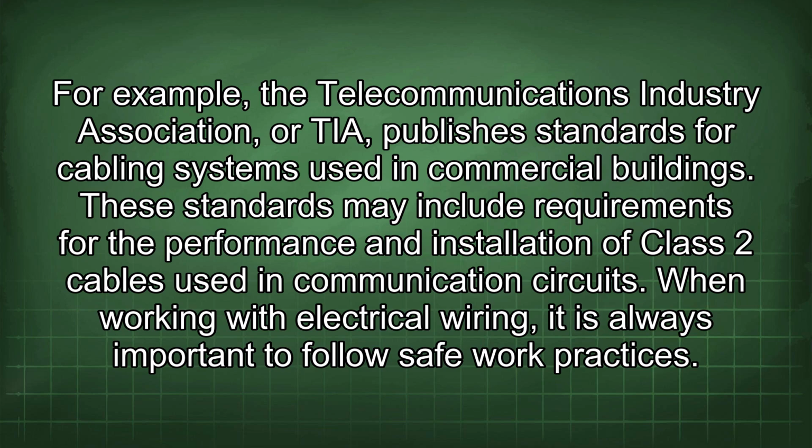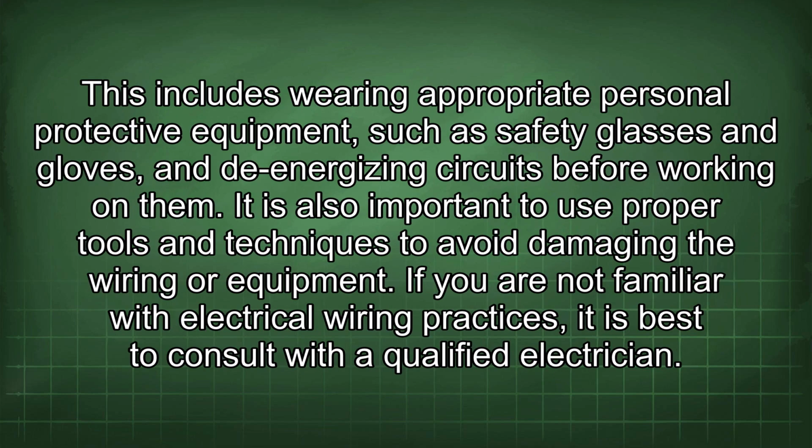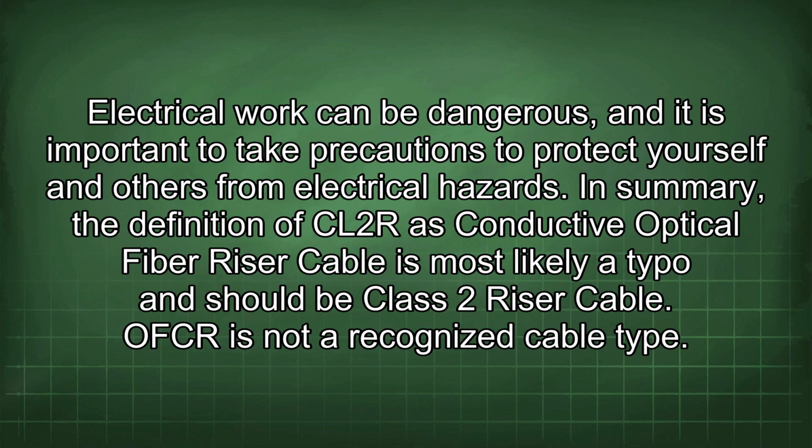When working with electrical wiring, it is always important to follow safe work practices. This includes wearing appropriate personal protective equipment such as safety glasses and gloves, and de-energizing circuits before working on them. It is also important to use proper tools and techniques to avoid damaging the wiring or equipment. If you are not familiar with electrical wiring practices, it is best to consult with a qualified electrician. Electrical work can be dangerous, and it is important to take precautions to protect yourself and others from electrical hazards.